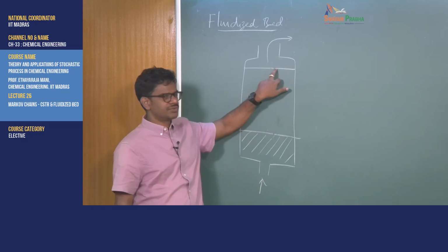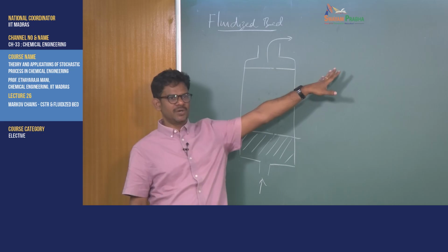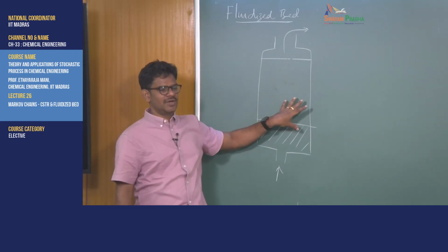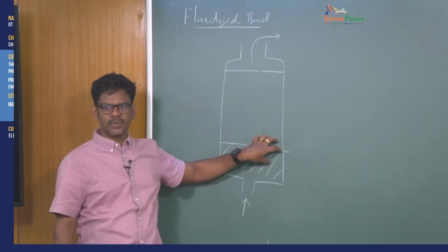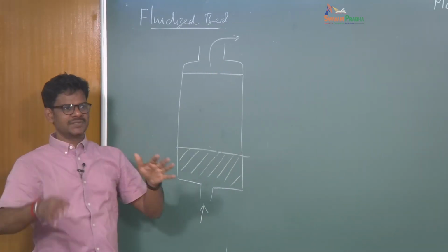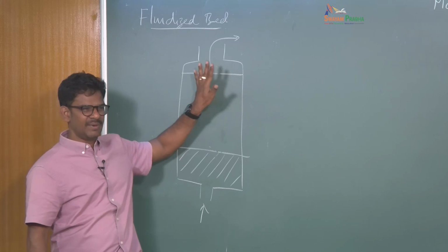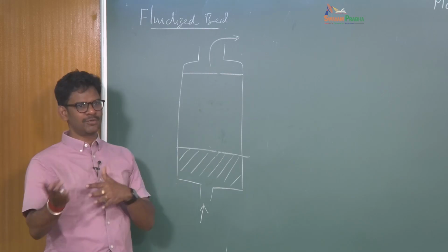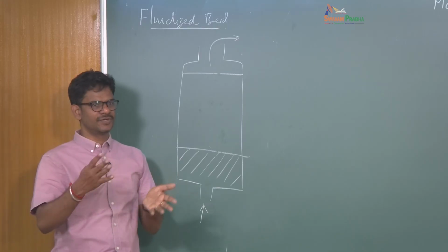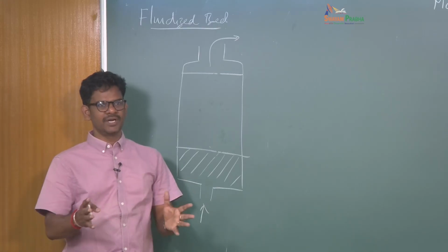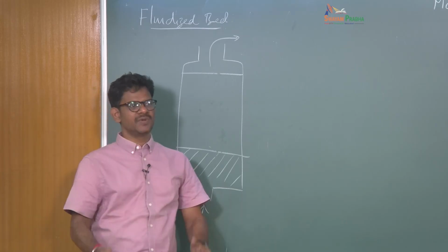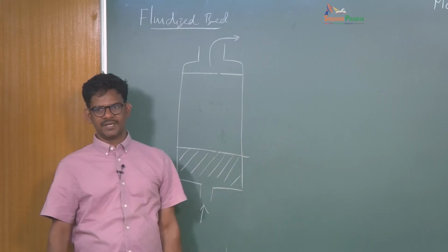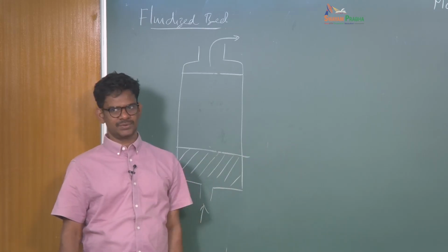When the particle comes close to the boundary, it has to be absorbed. We talked about another problem called diffusion-controlled reaction, or a gas molecule diffusing from a liquid and then evaporating. In those cases we talked about boundary conditions, and we are going to apply something similar here. As you can see, the principle is the same: diffusion plus boundary conditions, diffusion plus some sort of managing of the inlet, outlet and boundary condition. Otherwise the framework is very similar. You can apply it wherever you want: CSTR, PFR, packed bed reactor, fluidized bed reactor and so on.